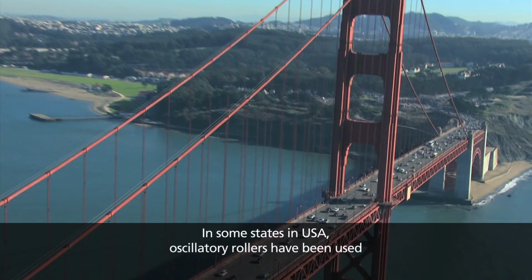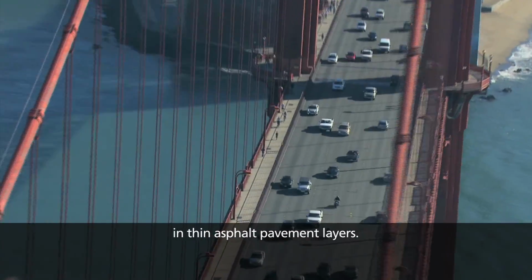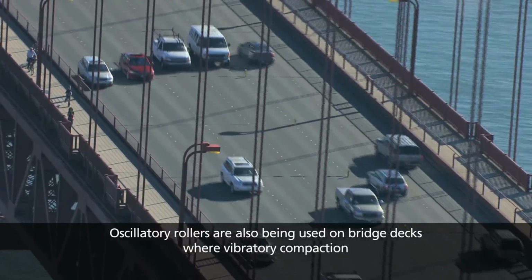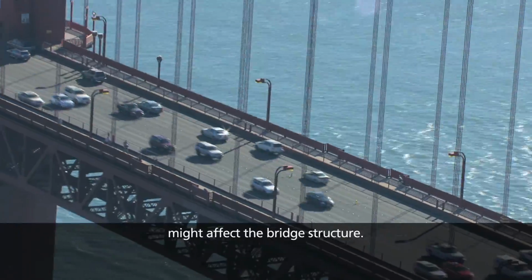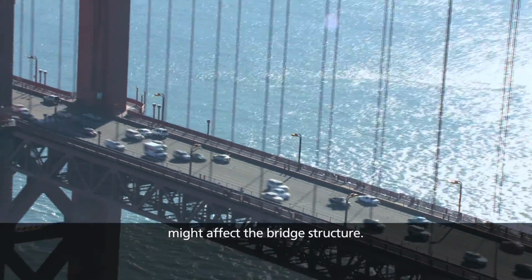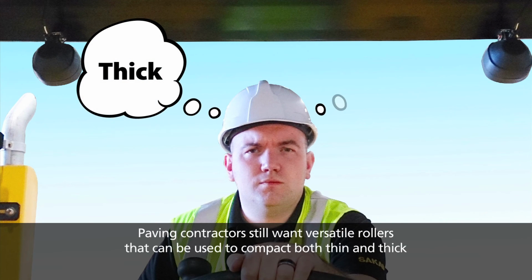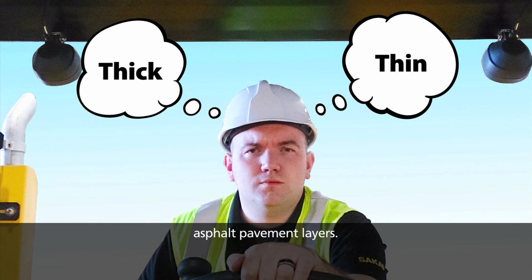In some states in the USA, oscillatory rollers have been used in thin asphalt pavement layers. Oscillatory rollers are also being used on bridge decks where vibratory compaction might affect the bridge structure. Paving contractors still want versatile rollers that can be used to compact both thin and thick asphalt pavement layers.